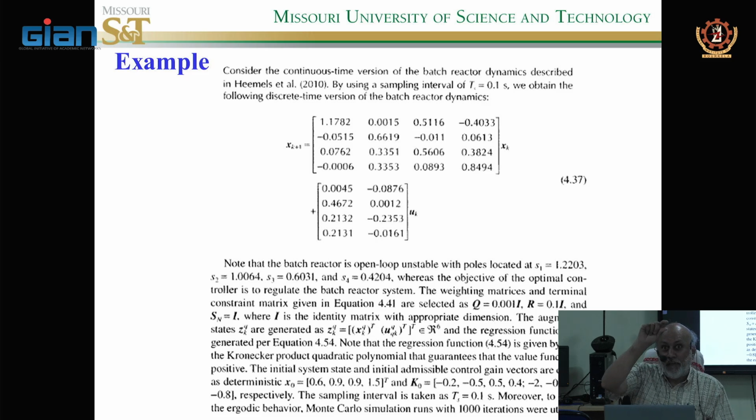So remember, you have a linear system, then you design an adaptive law, right? But then you compute the closed loop error dynamics, which comes with a theta tilde, which is basically the parameter estimation error. So why is it non-linear? See, that's the learning part. Because, you remember you're using that update law? That update law is non-linear because it multiplies.